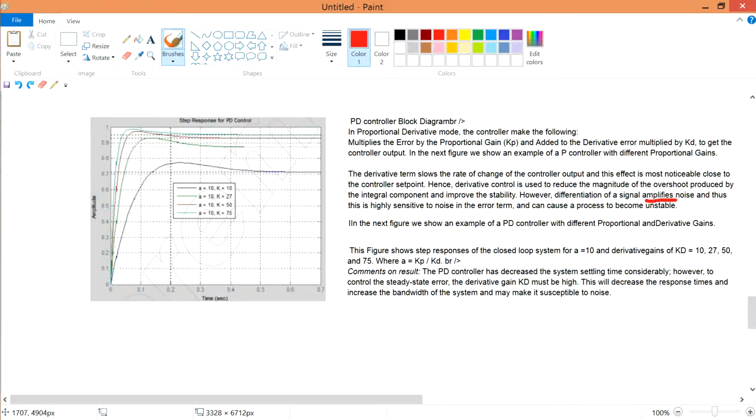I think you get what I mean, because the noise is embedded in your error now, and if you were to adjust your error, you're going to adjust your noise altogether. So your noise and error together, you make your noise and error somewhat the same magnitude, such that you are amplifying your noise, so your reference signal may not be exactly correct anymore, and this is the thing of it.